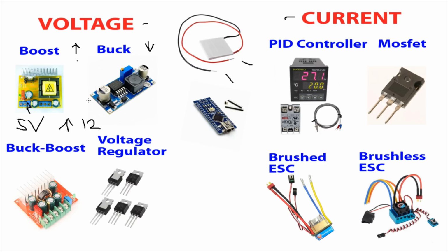Now, for controlling TECs, that implies that you have a lower input voltage than output voltage that you want. So say you've got, like I said, 5 volts input and you want it to be 6 volts. Now that obviously means that your input voltage has to be lower, but it also means you can't turn this TEC off with this, because all you're doing is taking the input voltage from a lower value and boosting it up to a higher value. So you have no way of actually stopping it. It's just a way of increasing the voltage.